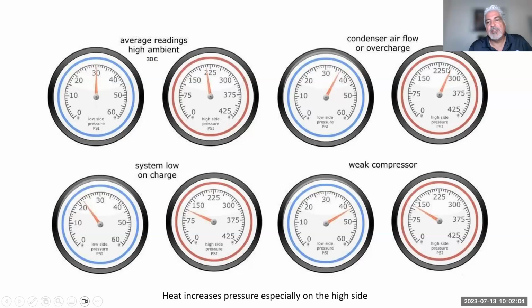It's getting cold. The 250 is about okay for our temperatures, but again, this should drop a little bit more. Now, I want you to understand something. When you look at the high pressure side, depending if it's a cold day, let's say it's a 70-degree day, it isn't surprising to see 200 or less, right? You might see 200 or less. And this one will be very low, getting very cold.